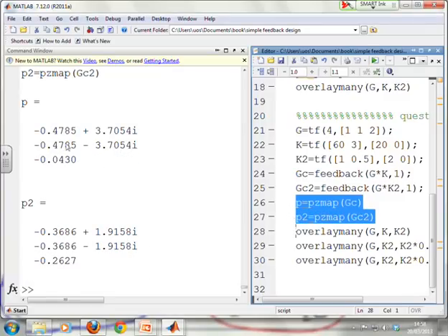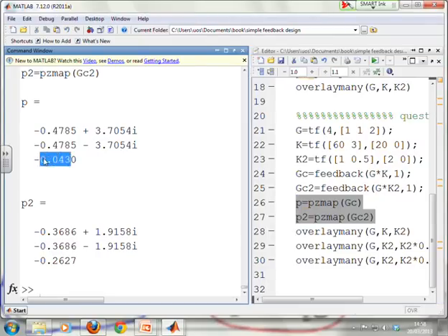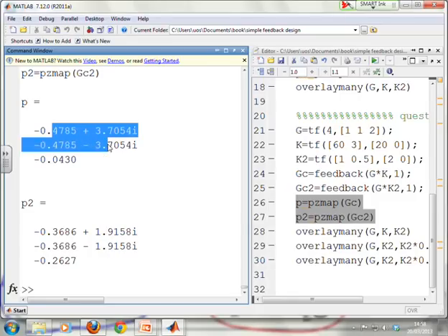With the compensator given, poles at minus 0.47 plus or minus j 3.7: very, very oscillatory, and also a very slow mode. That might not be surprising, because we said the ki term was too small, and the integral tells you about settling time. The kp was too big, and that might explain this rapid oscillation.